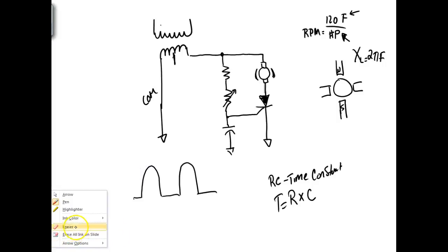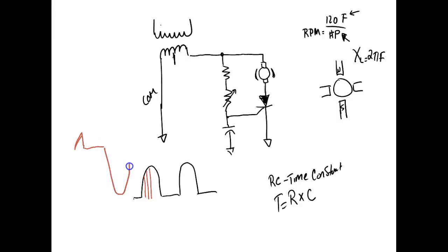Now this gets hard to look at with an oscilloscope. So if I do this, then this is the amount of AC the DC motor will see, and the motor will slow down. The problem with an oscilloscope, and y'all probably want to come up here, is that if I look across the SCR, I'm going to see when the SCR is turned off, right? You understand? So what we'll see across here is a little hump right here, and then it'll stay off, and then we'll see the whole negative alternation.